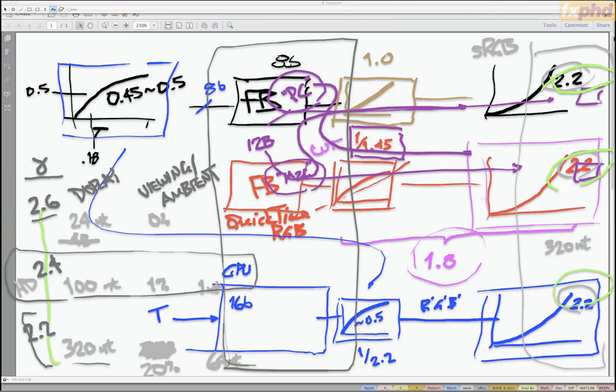And that function is more or less fixed by the construction of the CRT itself. And what you measure really depends upon the black level that you dial in, either as a calibration control in the signal processing or the black level knob or setting that's made available to the user. So as you bring the so-called brightness, or what I would prefer to call black level, on the display setting up, you are effectively dropping the value of that exponent.